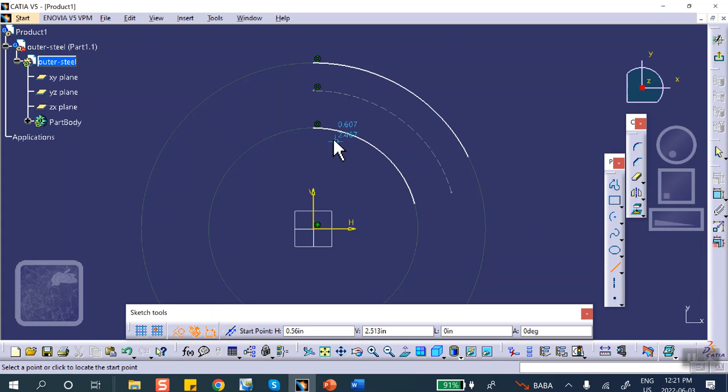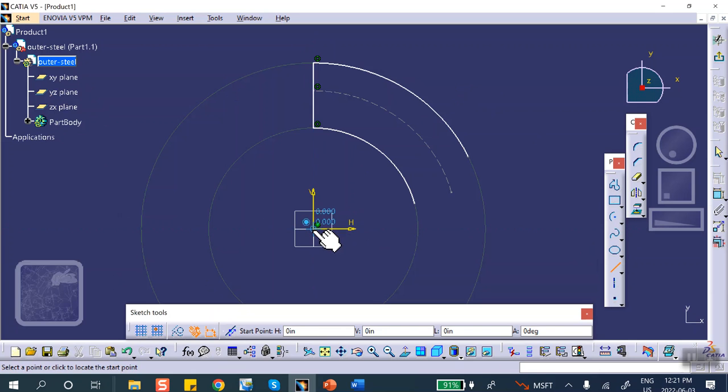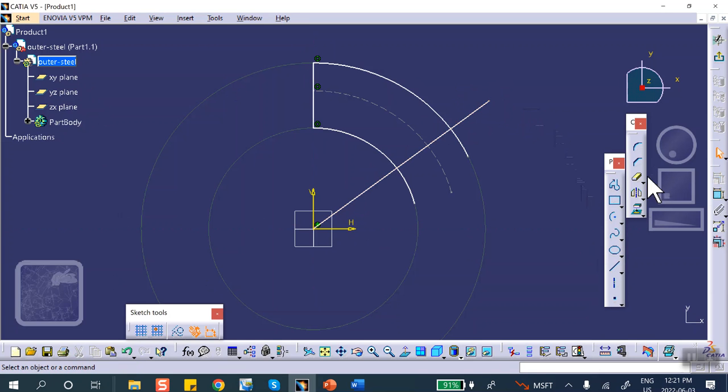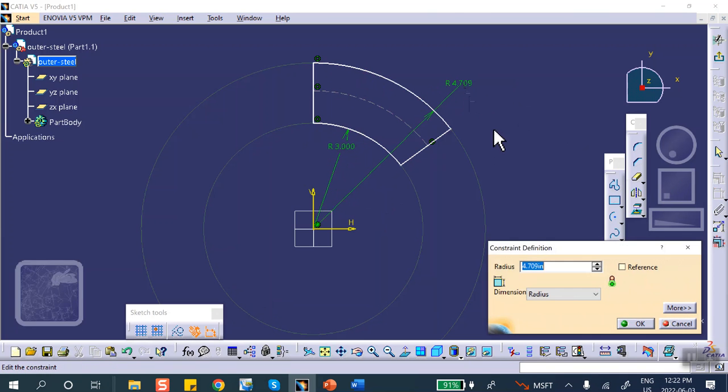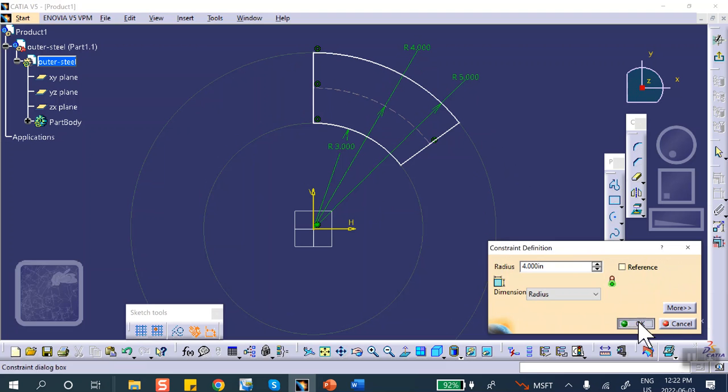Actually, let's create the geometry first and then put our dimensions. From here to here. This is not construction. Good. And then we draw a line from the center there. And let's do a quick trim, get rid of all the junk. We don't want that, we don't want this. This one doesn't matter, but we don't want it. All right, so let's put some dimensions here. This guy is 3 inches. This is 5 inches. And this is where the circle, the hole, is located, 4 inches away.